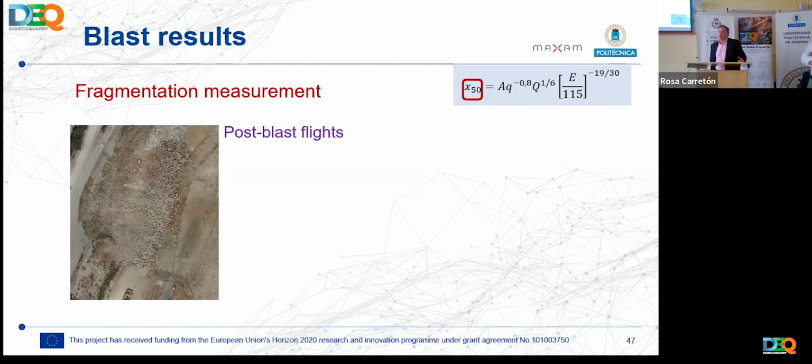Some of your engineers or some of your foremen, some person needs to be a drone pilot so that he or she can do the job. That's also inexpensive. It takes a couple of months of training in the afternoons. You can do most of that online. And it's like 100, 200 euro, the drone pilot course. So in the end, the flight itself and the preparation can take like 1 hour of this person, and then another hour of computer work, etc. So it's not a big deal.